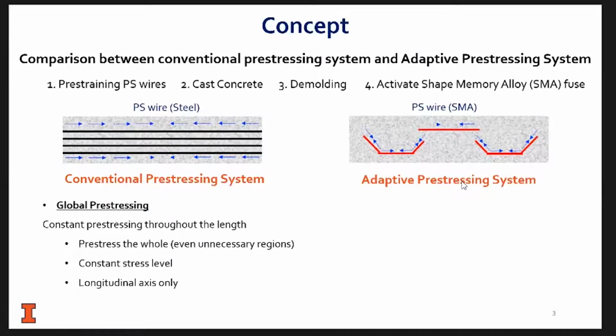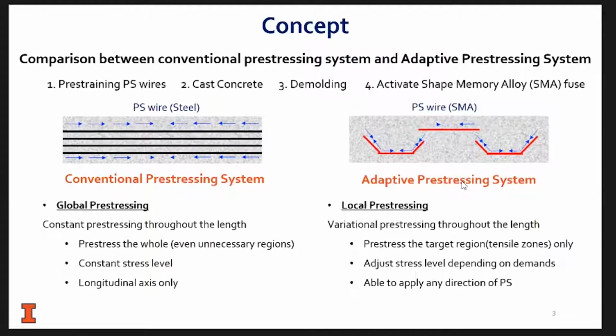Now, hypothetically speaking, what if we can switch to the design on the right? Basically, we can target specific locations where we can apply pre-stressing, at the center negative and rail seat positive primarily, and then maybe add a few pieces here and there as needed. But those are the two main primary locations. That is going to help us tremendously in not only localizing the pre-stress where it's needed the most, but also eliminating pre-stress where it's not needed, like the end region.